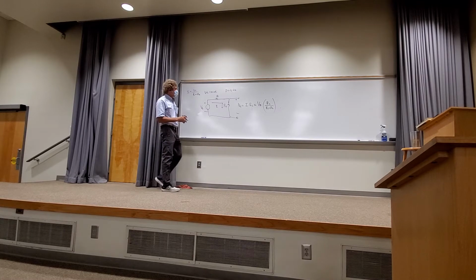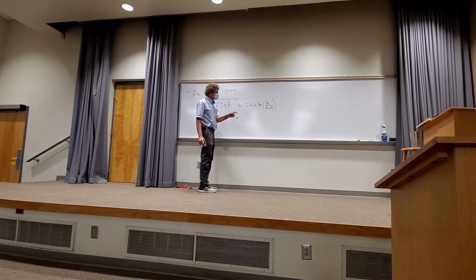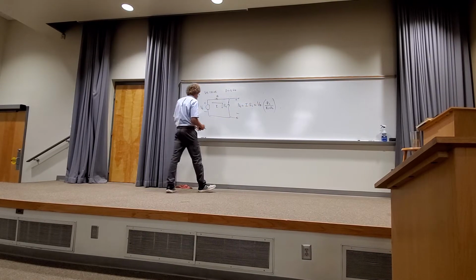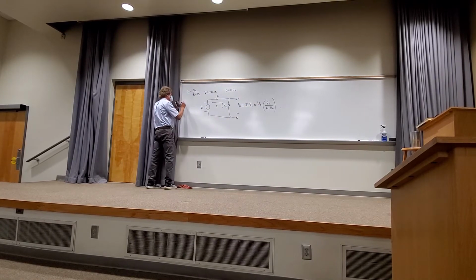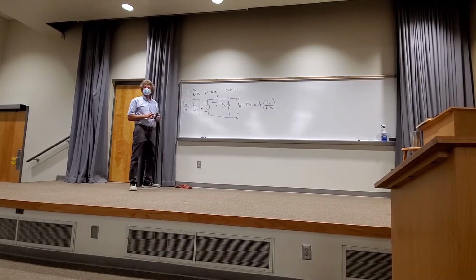It says the ratio of this voltage to the source voltage is just the ratio of the resistance where you want the voltage, over the sum of the total resistances. Said another way, V2 over Vs is simply R2 over R2 plus R1. And that's voltage division in a nutshell.